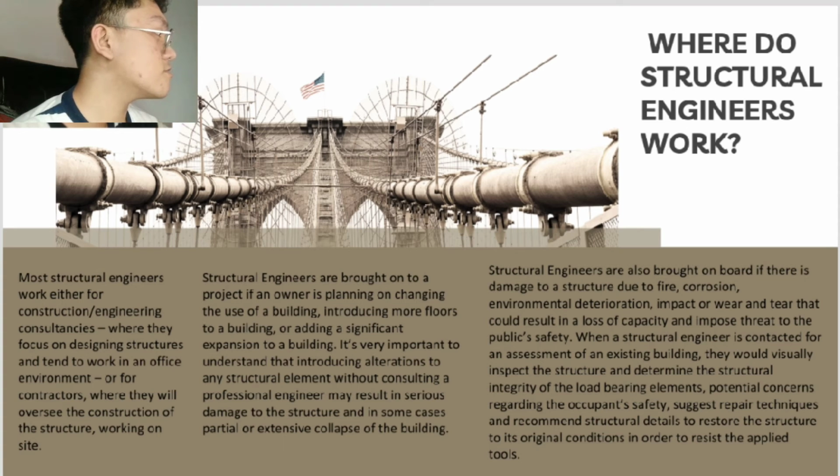Structural engineers are also brought on board if there is damage to a structure due to fire, erosion, environmental deterioration, impact, or wear and tear that could result in a loss of capacity and impose a threat to public safety. When a structural engineer is contacted for an assessment of an existing building, they will visually inspect the structure and determine the structural integrity of the load-bearing elements. They identify potential concerns regarding the occupants' safety, suggest repair techniques, and recommend structural details to restore the structure to its original condition in order to resist the applied loads.